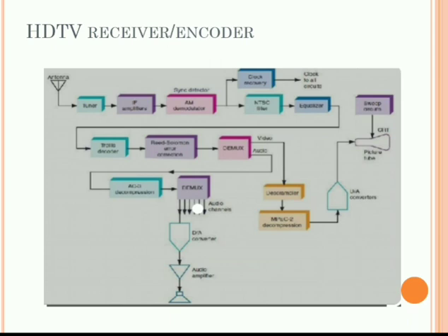The audio signal here is also demultiplexed and fed to the AC decoder. The resulting digital signal is fed to the D to A converter. The decoder decodes that particular audio signal, which is passed through the D to A converter for the purpose of gaining the audio signal, creating the analog audio for each of the 6 audio channels.